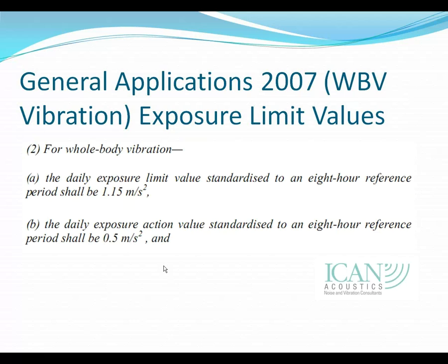Okay, so moving on then, looking at whole body vibration at this time, and back again to General Applications 2007, you'll notice this is very similar. It's again based on a daily exposure limit value, standardized to an 8-hour reference period, and it shall be 1.15 meters per second squared. And again, you'll notice that vibration level would be a lot lower than the hand-arm vibration acceleration values. And again, simply, you're exposing the whole body to this. So again, you'll notice that there are daily exposure limit values, and of course action values.